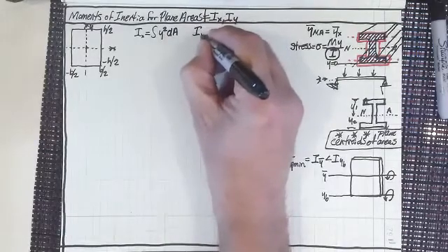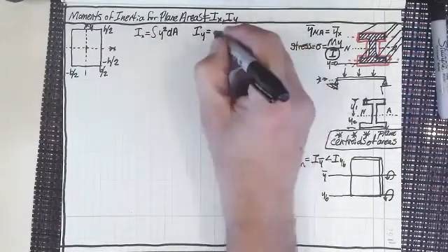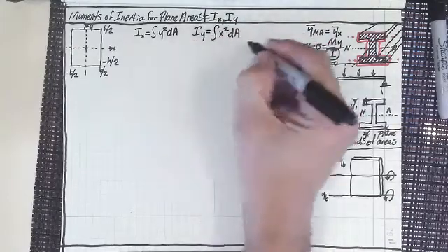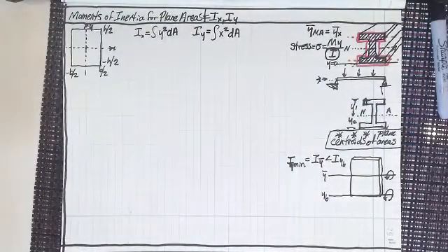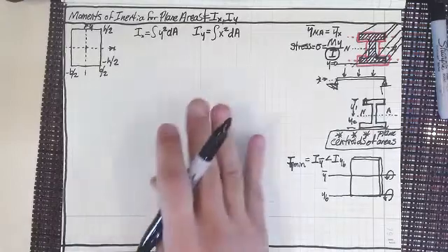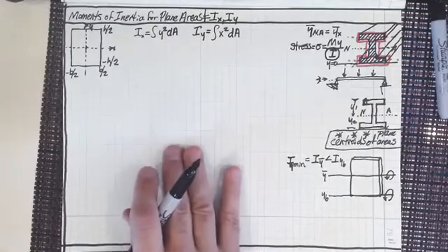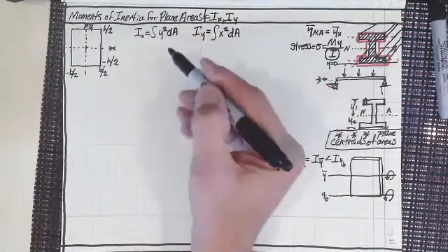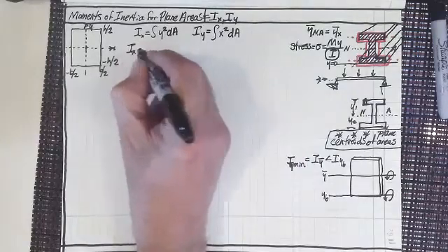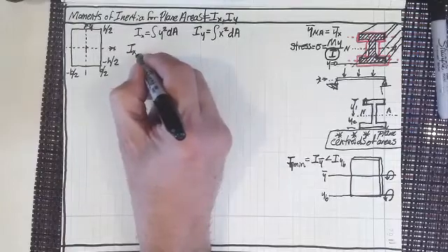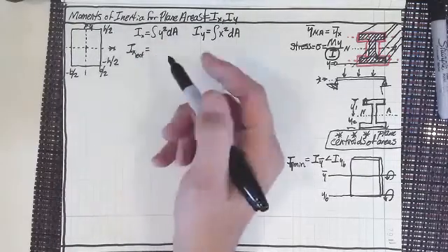And the moment of inertia about the y-axis is going to be the integral of x squared dA. We've seen similar integrals like this when we were working with the centroids, right? And so here we see it again. So the first thing I want to do is just derive using this. Let's just look at I of x for the rectangle that I have here. I'm not going to write "rectangle" all the time though.